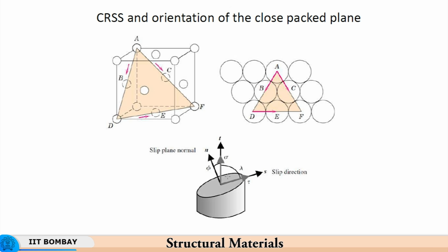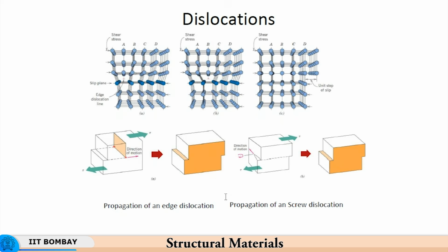So wherever the material flows, as it is called. So here, for example, the material will slip, and therefore material will flow so as to cause permanent deformation. So wherever you need permanent deformation, you would orient this plane parallel to this, so that the permanent deformation happens easily, because the idea is to cause permanent deformation.